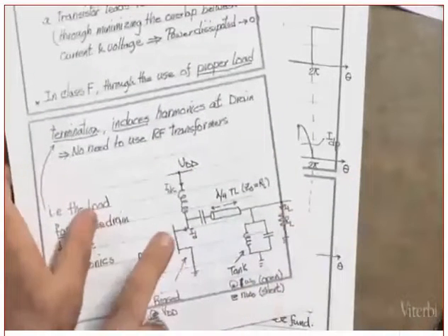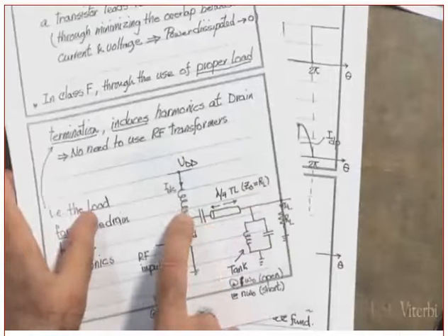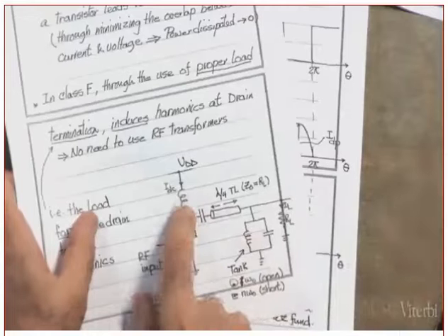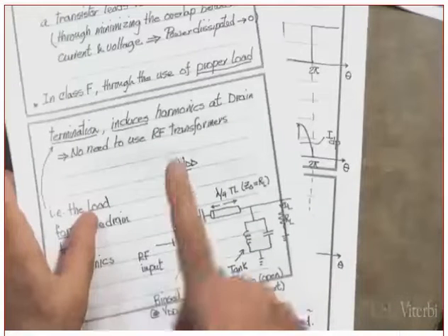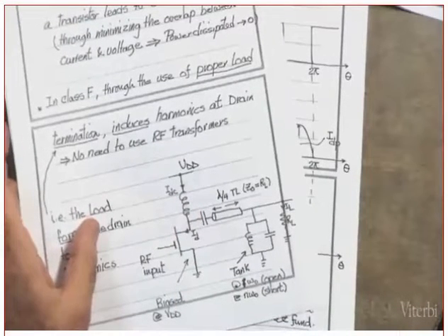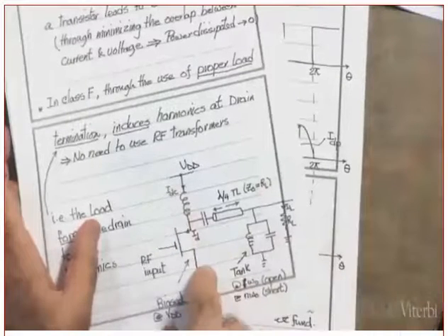The AC, by the way, you either go this way or you go that way. But the DC, this one will block it. And this one, as far as the DC is concerned, is a short circuit. The RFC, the RF choke. And because omega equals 0, you get j omega L, yes? So at DC, omega 0, DC will come here.